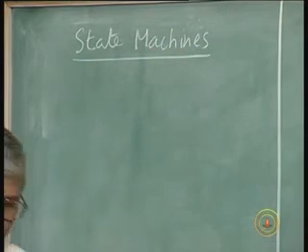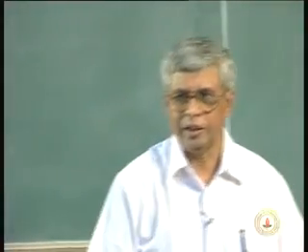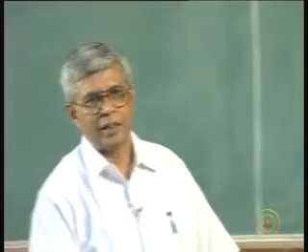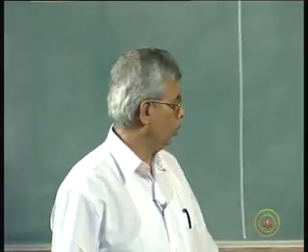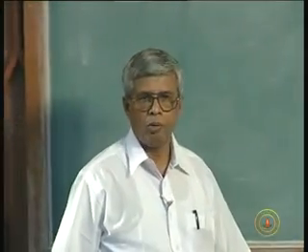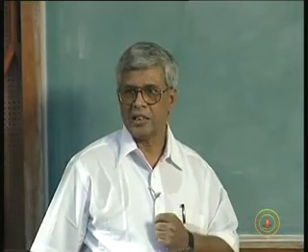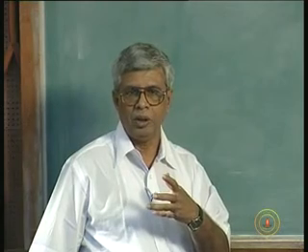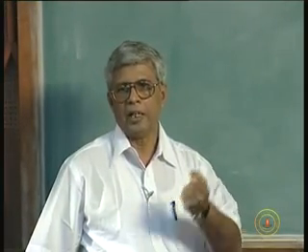This comes from the good old days of machines. A computer was called a computing machine, right? So everything was a machine. A state machine is a circuit or a system, whatever. As I said, let us not be too specific about it. It has several states in which it can exist, and a clearly defined set of inputs which will steer the circuit or the system from one state to the next state, and in each state it can also produce an output.